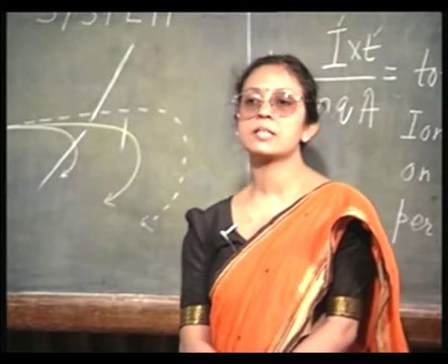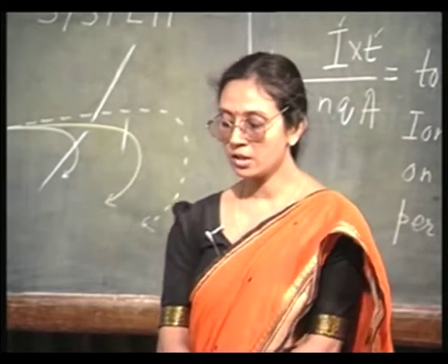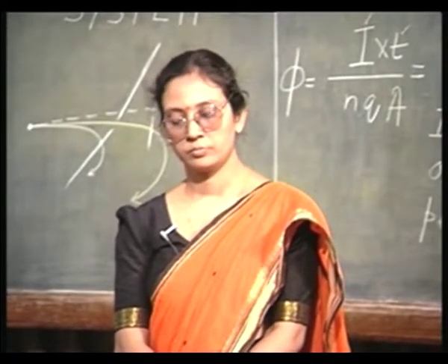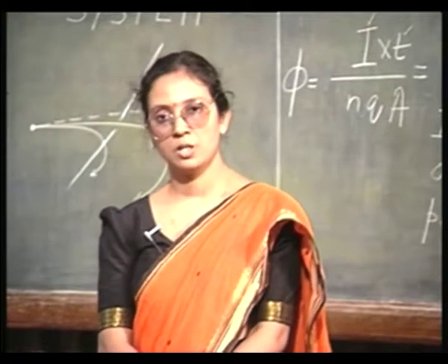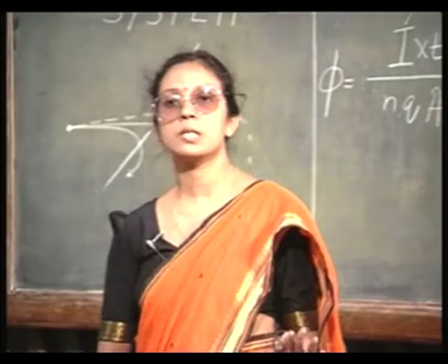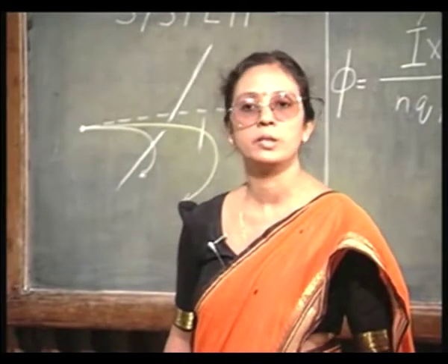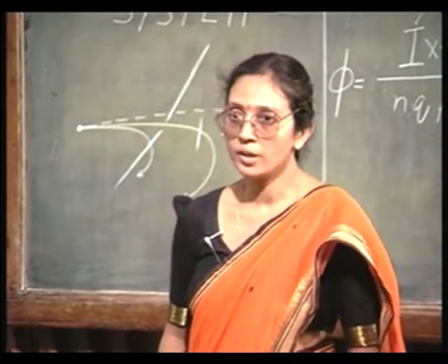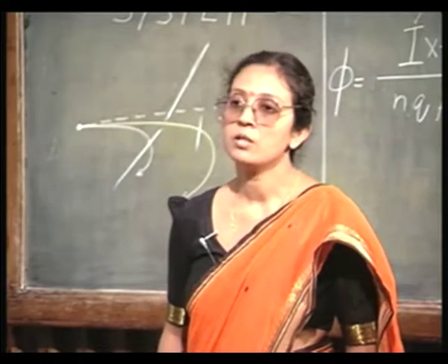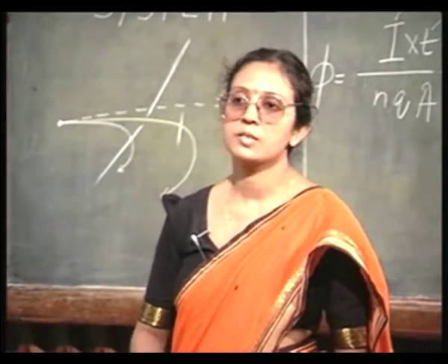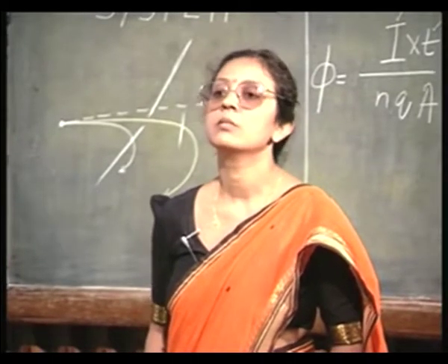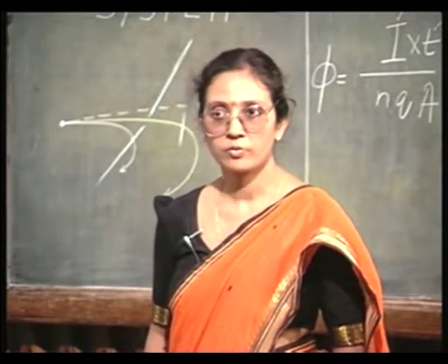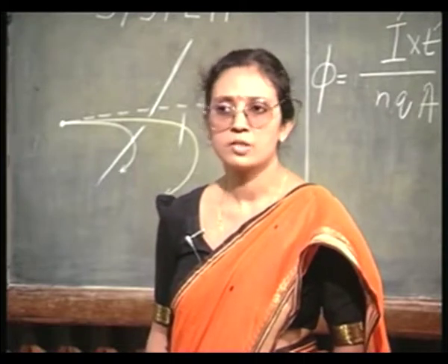Now, for silicon this value of ED is 15 kilo electron volt. And for implantation we frequently use energies in excess of 100 kilo electron volts. So, you can understand how much damage there is going to be created, how many displaced lattice atoms there will be. So, obviously the host atoms are displaced from their original lattice site, they will create a vacancy as well as an interstitial. So, that means a Frenkel pair. So, a lot of Frenkel pairs can be generated, lots of damage will be there.